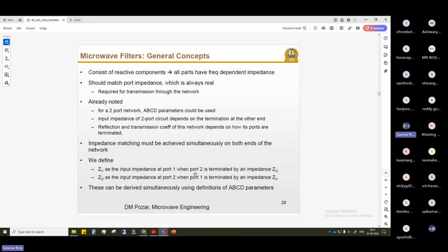Okay, so now we are coming to filters. Filters, as you know, are very important in RF circuits or any circuits because many times we play with the frequency, right? Where is the main use of filters? In our communication transceiver circuits, we need low pass, high pass, and band pass filters. Everything is required in a normal transmit receive circuit chain, before and after sampling, and in transmission before the antenna we use a band pass filter.